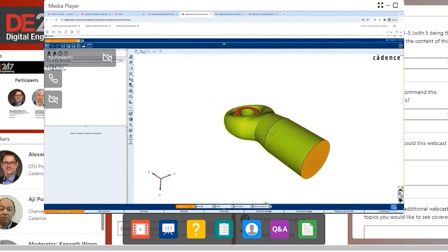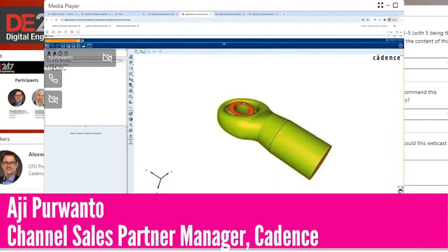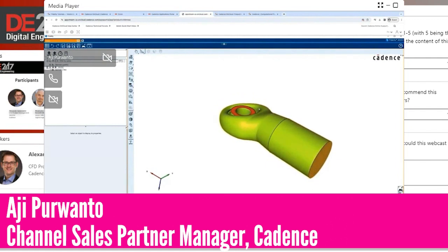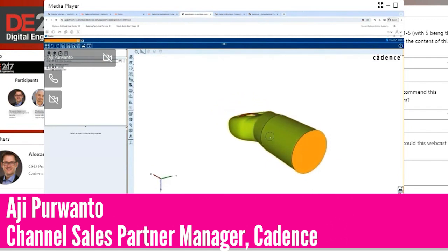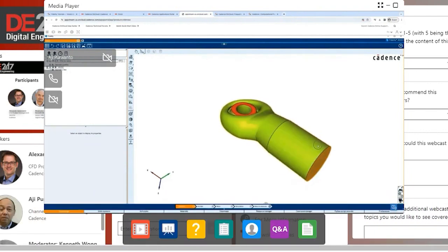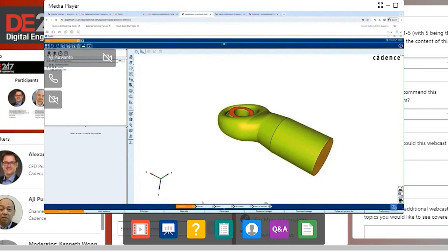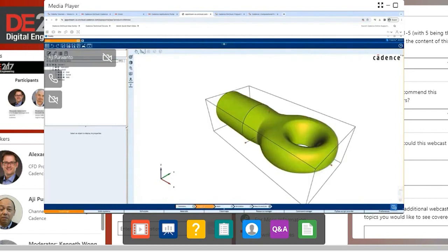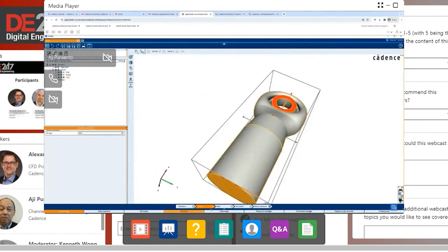We go now to the geometry preparation. You have a flow coming through the inlet, the red one, and then it will circulate inside the volute and go out from the outlet, the orange plane there. We are now preparing the domain. The domain is where the flow will go. You see the seed point here, and the seed point is well located inside the domain, so we have a good domain to start the meshing part.